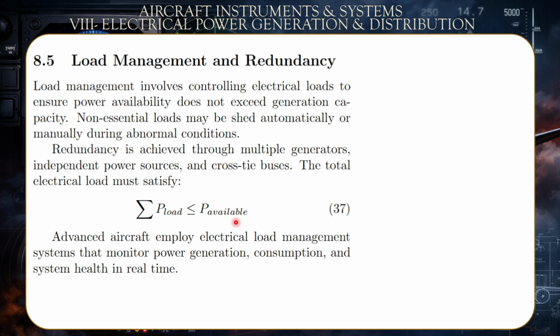Otherwise, non-essential systems would be taken off the power array immediately and automatically via the intelligent mechanism of their circuit breakers. And even the electronic system would trigger that in order to ensure there's no overconsumption of power that's not available, which would starve the different instruments and they would start working abnormally.